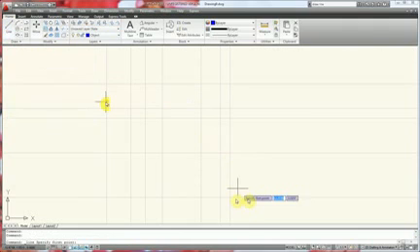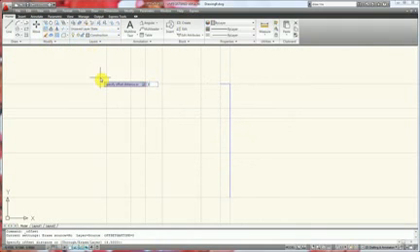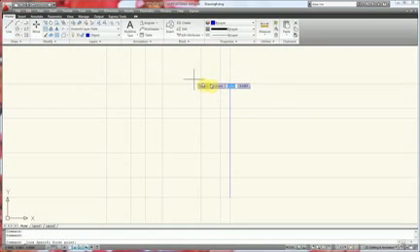So I'm going to start on the side and I'm going to go up the side and over. Oh, we forgot one construction line. I'm going to switch back to my construction layer, go to the offset, switch back to my object line, and then continue on with my object.